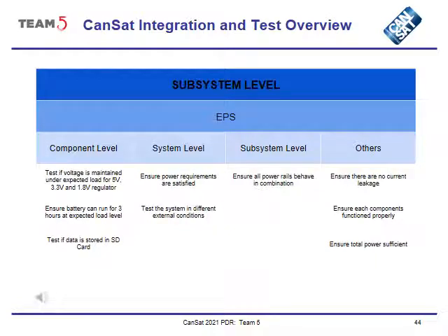EPS. For component level, test if voltage is maintained under expected load for 5 volts, 3.3 volts, and 1.8 volts regulator. Ensure battery can run for 3 hours at expected load level. Test if data is stored in SD card. For system level, ensure power requirements are satisfied.